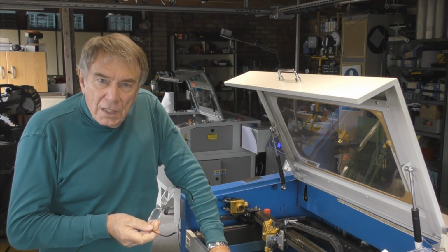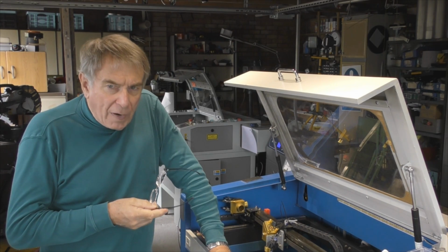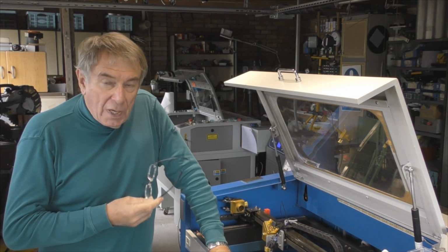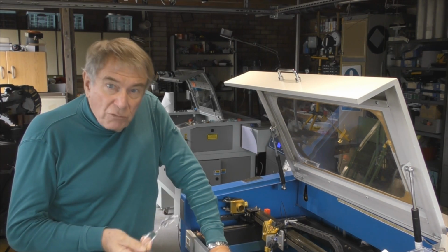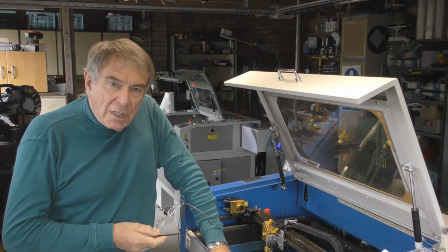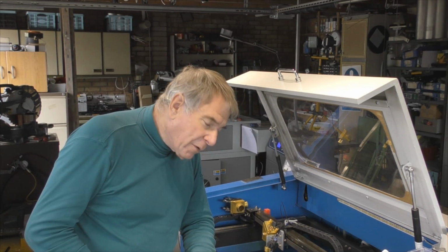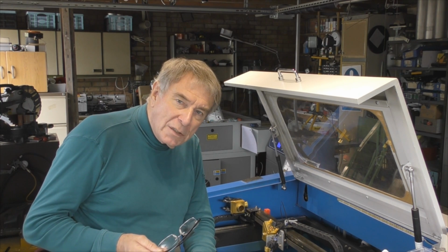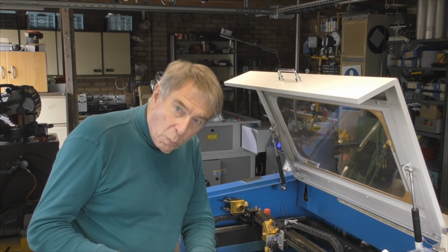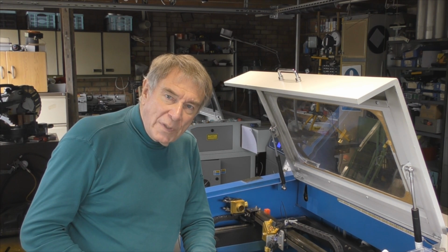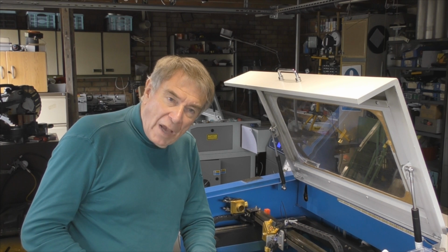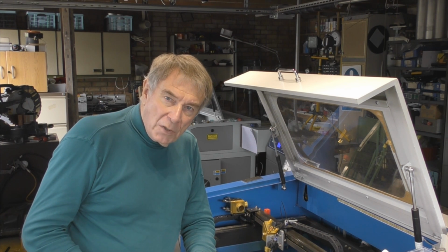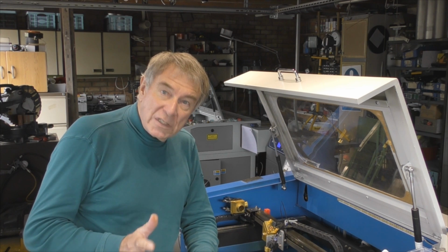Just recently, somebody sent me an RD file, and I was rather puzzled at what I saw. It was a very nice picture, low resolution, not running at too high a speed, but it had been dithered. As well as dithering the picture to produce black dots on a white background, the program had also been set up with output direct, and we had a max and a min power set. Now, the output direct and max min power would indicate an attempt to do grayscale engraving.